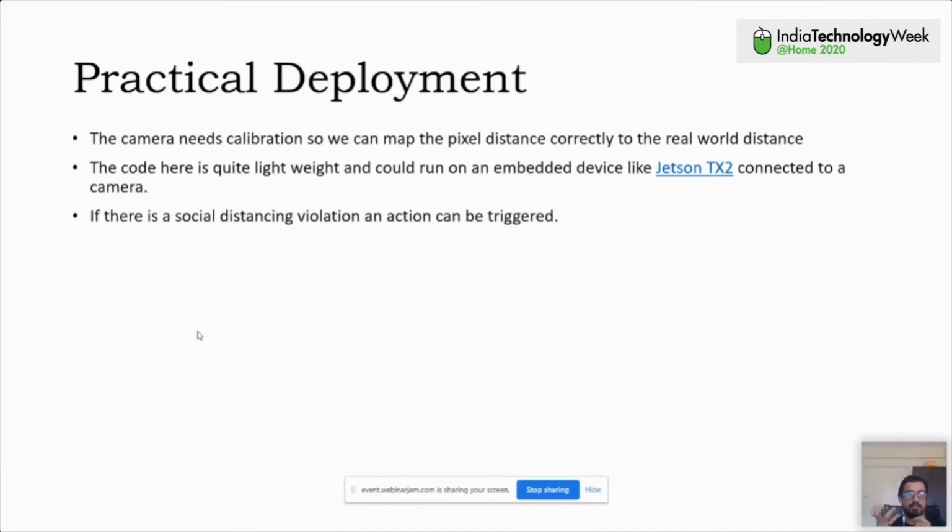Second, given low-resource computation power, like embedded devices such as Raspberry Pis, Jetson Nanos, and Jetson TX2, it can run very well, and you can achieve an FPS, frame rate per second, of say 40 to 60. That's very good to achieve on a lightweight processor, and that's where SSD models are the favorites when you talk about object detection on embedded devices.